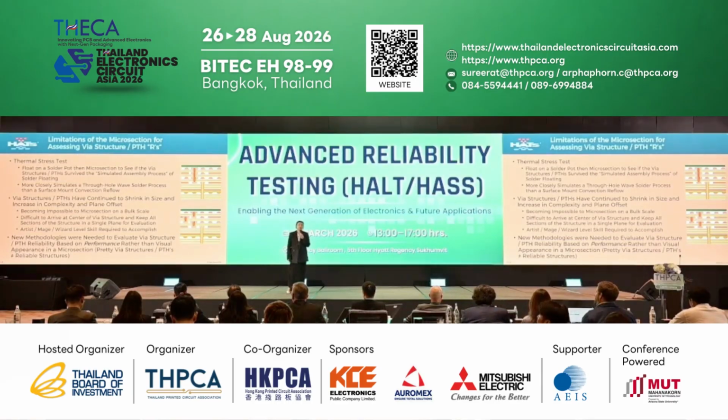In old times, when there were a lot of PTH holes, people did microsection like hundreds, sometimes thousands every day, because that's just easy to do. The holes are so big, easy to take the area, cut the area, and do microsection easily. However, when PCB and all the via structures are getting smaller and smaller, it's almost impossible to do a lot of microsections on these microvia structures in huge quantities. Just impossible.